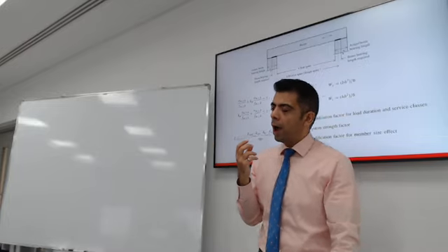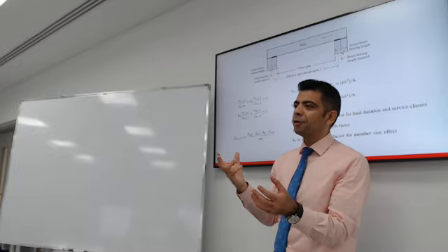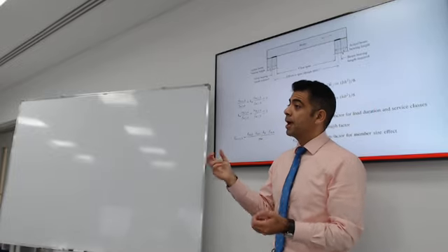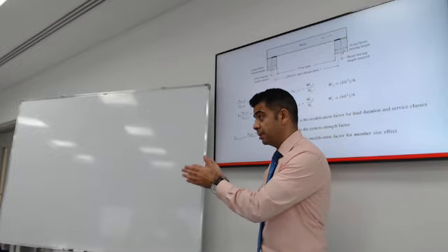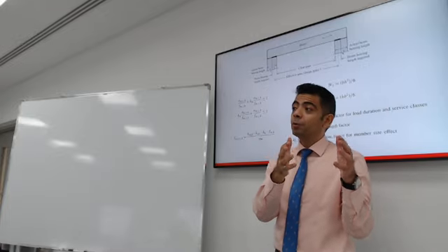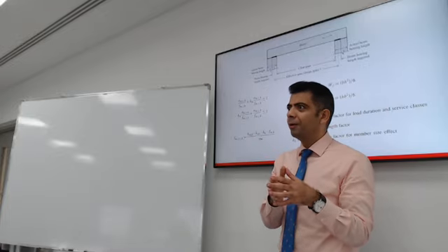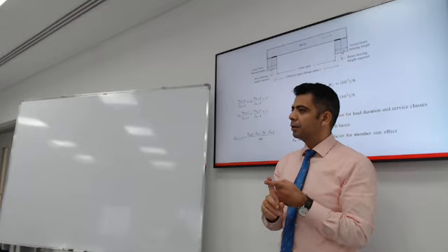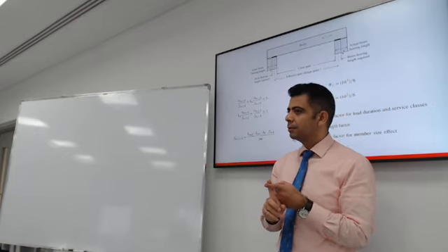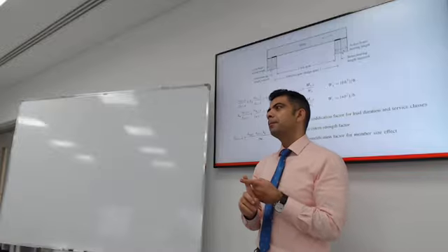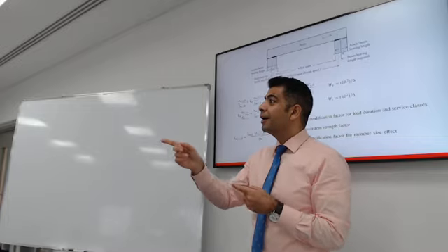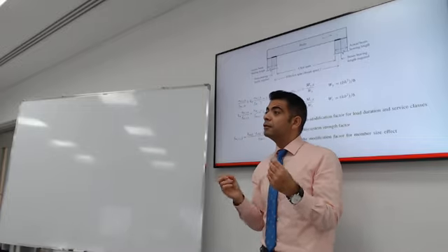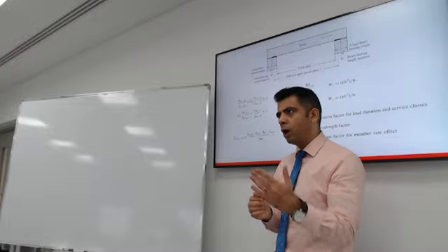So which factor of safety you think should be bigger? Factor of safety when working with steel material, or factor of safety when working with wood material? Wood. Why is that? It's a weaker material. It's susceptible to more damage. It has different variations. It's very difficult to get consistent quality of wood.